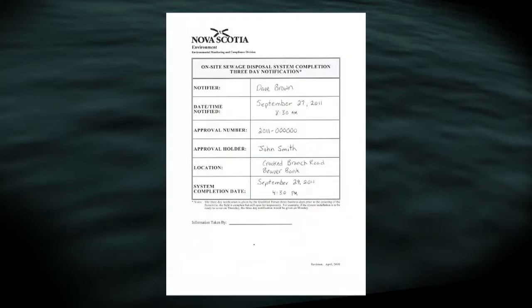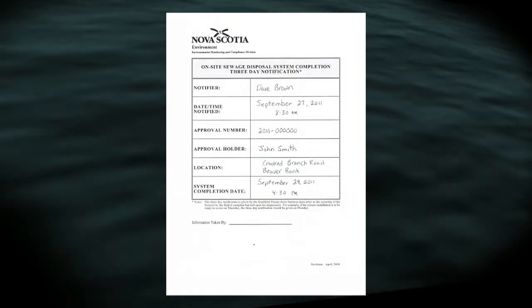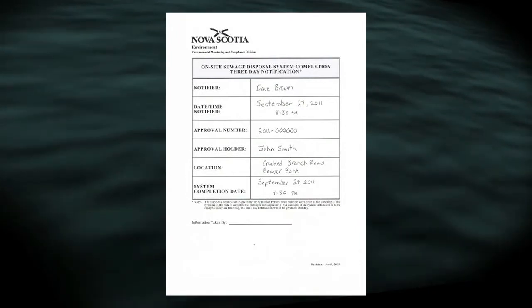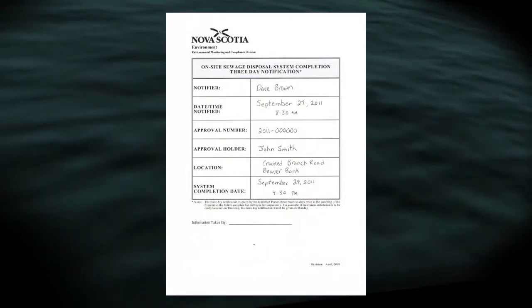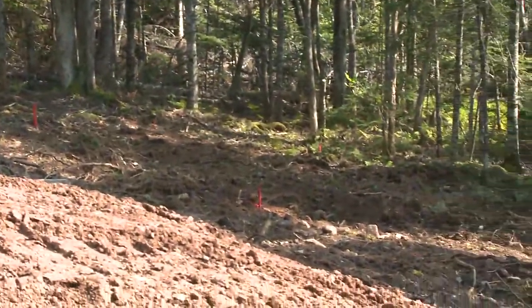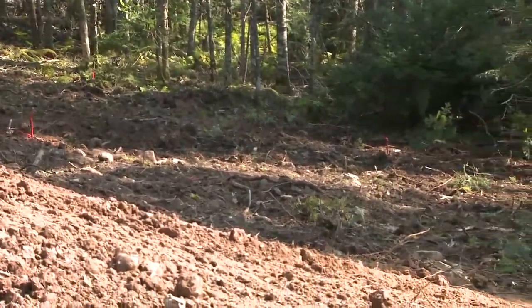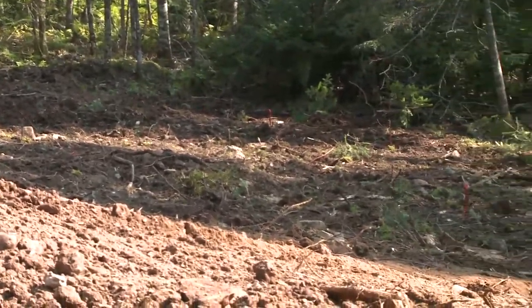The installer contacts the QP2 and advises that he is installing the system and of the date that he will have the system completed and left open, ready for inspection. The QP2 will give Nova Scotia Environment 3 days' notice of this date. The contour is staked in the proper location and the downslope buffer is scarified before beginning to place the sand.